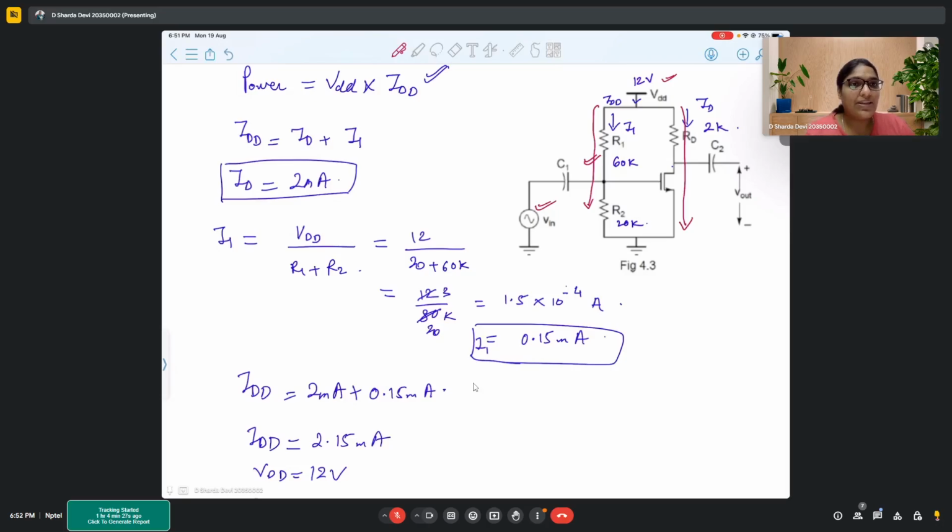That's why, to make things easier, we never call VDD or the supply input DC power, input power or input voltage. We always call it supply voltage. And whenever there is a term called input, it always signifies the AC signal that you give to the input terminal, which basically gets amplified at the output.